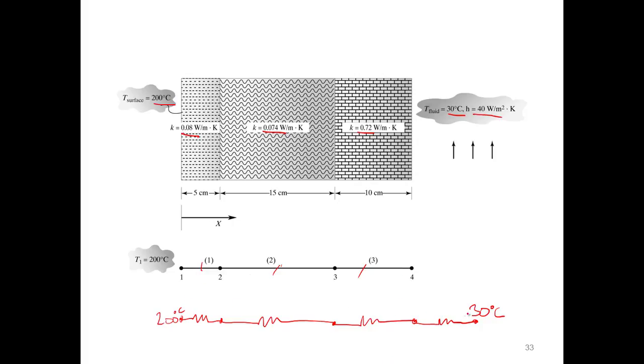So between all these resistances, these different materials, different modes of heat transfer, there's a constant Q dot. Just like with an electrical circuit, there would be constant current through all these. There's a constant heat transfer rate through all these heat transfer modes, different resistances of either material or via the convection. So let's see if this Q dot holds true, that it's constant for all our cases. It's kind of our check here.